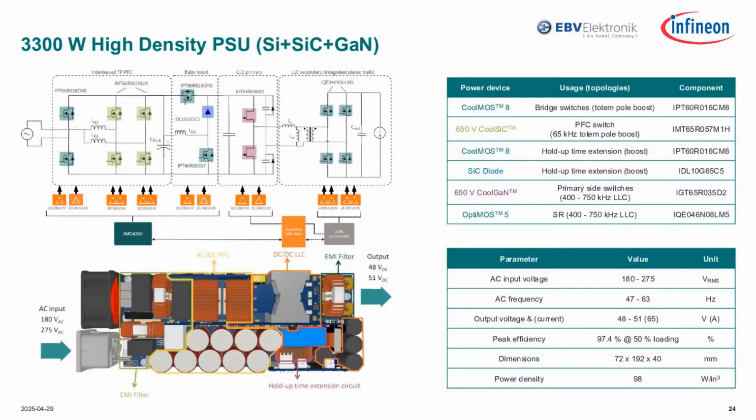And again, silicon comes back as the synchronous rectifier. It is because you need to balance between medium voltage gain and silicon. If the device is below a certain voltage, we understand that silicon still has an advantage, with good performance for synchronous rectifier applications.